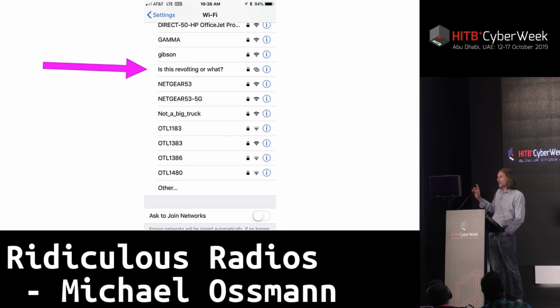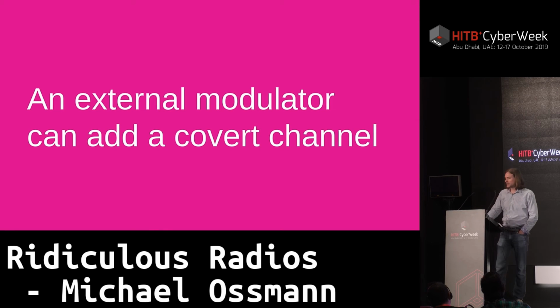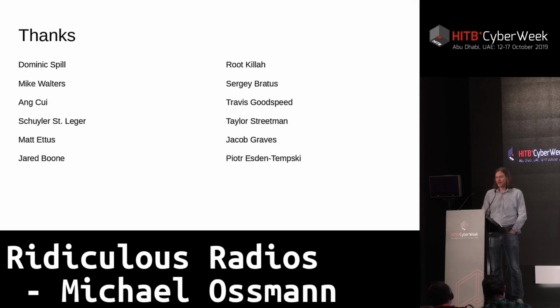So this was actually a fake Wi-Fi network produced by a Bluetooth dongle. It had no capability to transmit Wi-Fi. It was just transmitting an unmodulated test carrier, and then we were switching back and forth between two different length delay lines. And with that simple technique, we were able to improvise something that could transmit data that was seen as a Wi-Fi beacon by my phone. So an external modulator can add a covert channel onto any existing radio system, any existing radio transmitter.